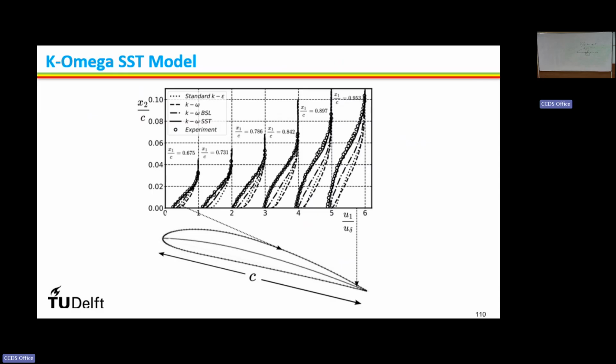At this location, you look, the boundary layer is getting separated. In this separation location, you will find the flow is coming and this kind of eddy structure is forming. This is the aerofoil. Once the uniform flow comes and hits it, it will pass like this, and here you will form some eddy structure.